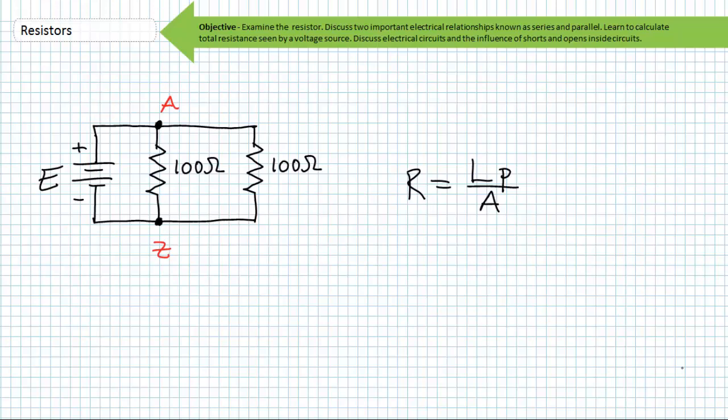This arrangement is not nearly as easy to understand and requires some visualization skills. However, I've got a trick up my sleeve in the form of our previous discussion on the three properties that determine the resistance of a conductor, namely length, resistivity, and cross-sectional area. Notice the emphasis. If you've got a single resistor connected from node A to node B, and if you add an identical resistor in parallel to this first resistor connected to the same nodes, think about what Johnny conventional current electron sees when he emerges from the positive terminal of a voltage source and enters node A. He sees not one, but two open and accessible doors.